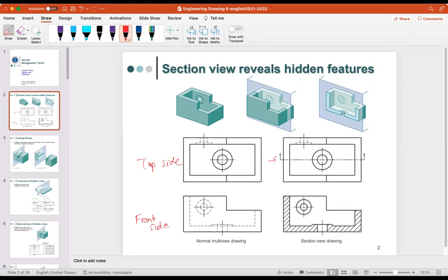We have the center point, and then we cut it. This is denoted with the plane, the axis, and then we put the phantom line, sorry, this straight line and then small line and then straight line again is called a phantom line, if you remember. This is to cut them for a section view.